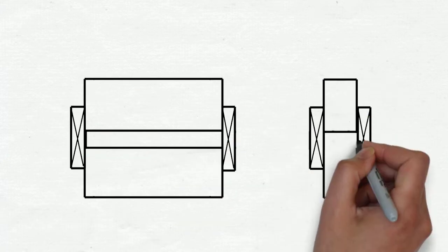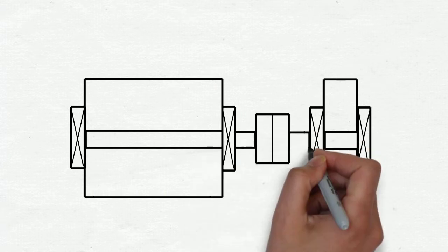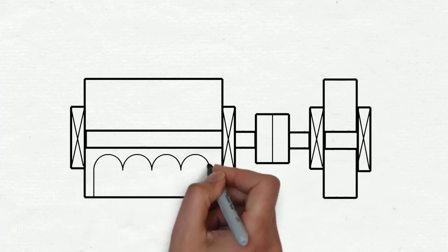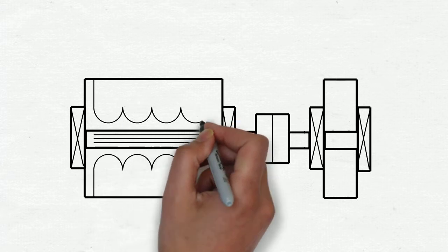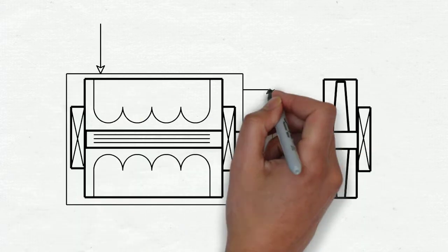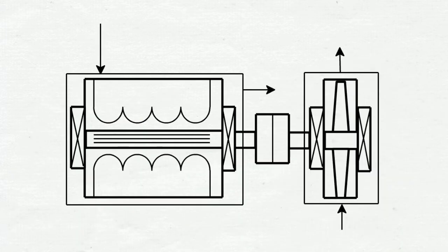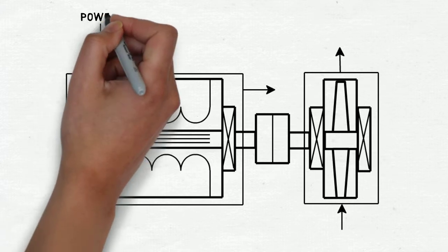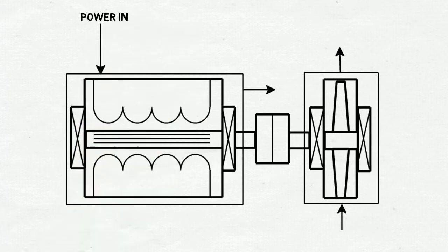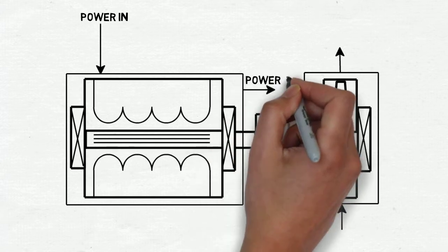In this short video, you will learn how to select points for APR models for a typical horizontal pump motor combination. Let's begin by sketching the motor, pump, and coupling arrangement. We'll continue by drawing our inputs and outputs. The motor has an input of power, conversion of electrical to mechanical power, and finally output of that mechanical power to the pump via the shaft or coupling.